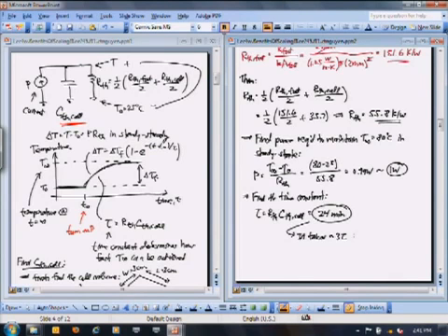Okay, like tau, right, gets you up to a certain amount, 60% or so. Then you have to wait a little longer for that thing to actually reach the steady state. And so if you're really interested in a stable system before you're using it, like a stable spectrum analyzer, you've got to wait 3 times that time constant to make sure that it's steadied out, right? There could be oscillations, too, in the problem. So you want those to go away.